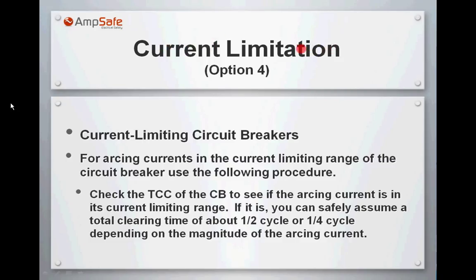Very good. Now let's talk about working distance. Working distance has a very interesting effect on the calculation of arc flash incident energy. We know what working distance is, and we're not going to be talking a lot about what it is, but how this working distance will have an effect on the arc flash incident energy. The working distance obviously depends on two things: the type of equipment and its voltage. That's how you figure out the working distance for the arc flash incident energies.